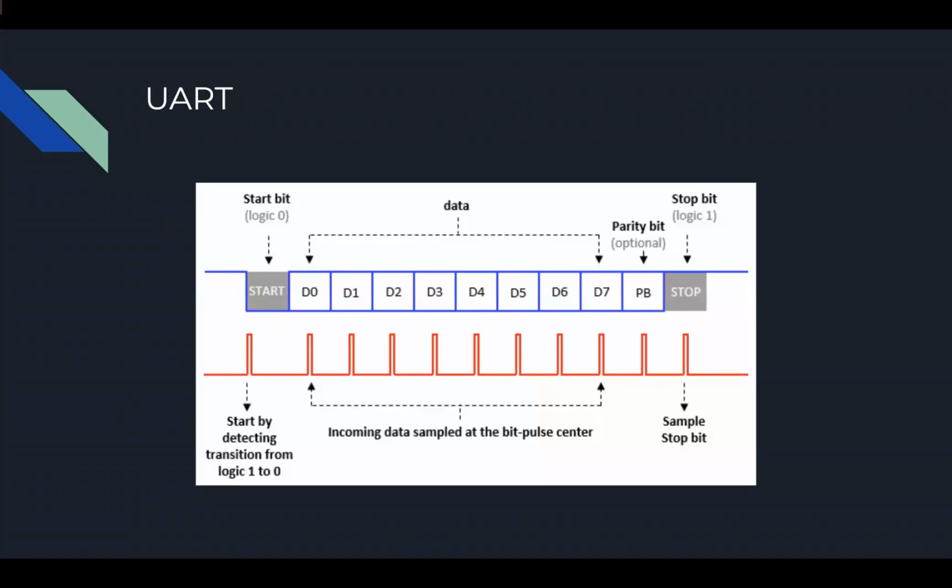So this is just an example of what UART would look like. See how they show logic 1s and logic 0s. It's because if you were looking at that on an oscilloscope, which shows you voltage over time, it would literally just be the signaling level, which would usually be 3.3 or 5 volts, or 0. That's what you would see, and it would look exactly like this. This is just an example of what one of these things would look like on an oscilloscope.